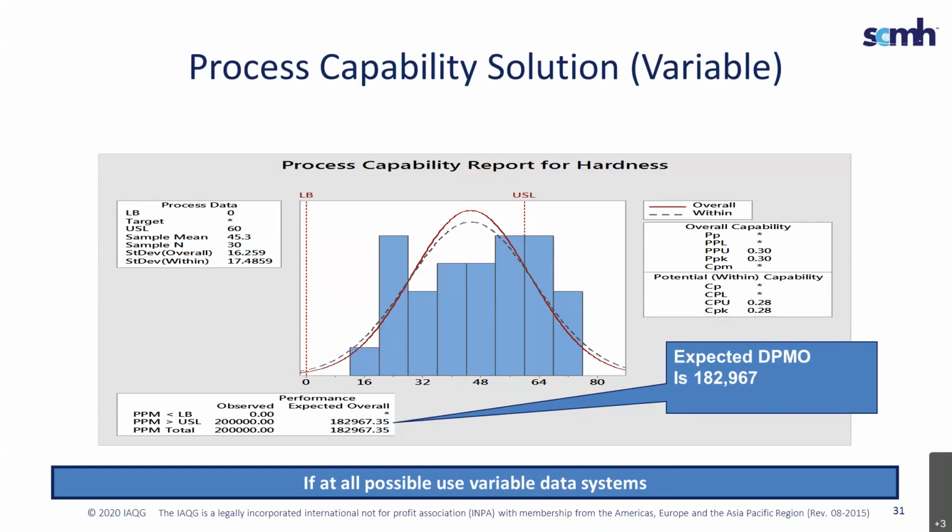If you need a 6 sigma process, CpK of 2, that means that you either reduce the variation so you have 6 standard deviations away from your upper spec limit, or you move the center away so it's 6 standard deviations away. Again, if you want a 6 sigma process. So if you can't center it, it's fine. You've got to reduce the variation, but you also have to understand what your acceptable risk is, what CpK you're shooting for.